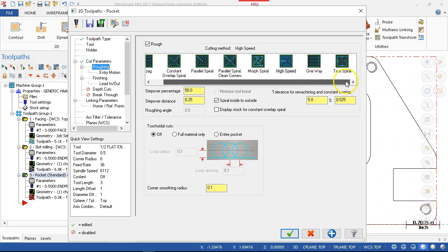The true spiral, that basically starting at the center and moving out. Each of those spirals is going to generate a point. It's not going to be a G03. It's going to be XY, XY, XY, XY, XY, and this will probably, even on this side, generate 1,000 lines of code. Something along those lines. It will be flying across because it'll be very small increments of movement.